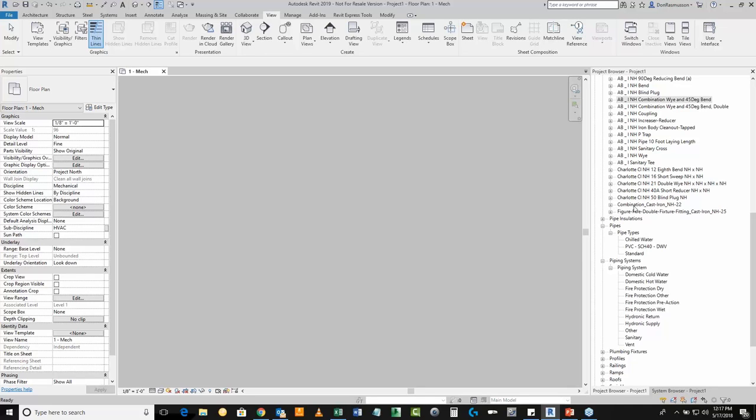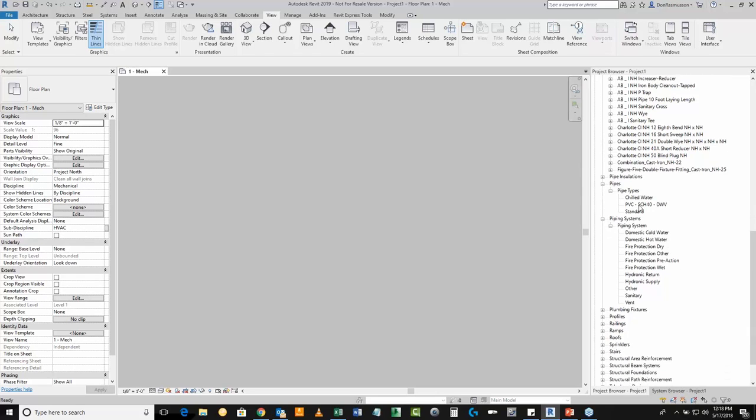The first thing that we have to do when we're thinking about setting up a pipe type and then setting up the routing preferences based upon that pipe type is to probably create a different pipe type, right? For those of you who've caught my previous webinars and or mini trainings, I go into depth about what pipe types are versus what pipe systems are. But pipe types are basically your materials and or your routing preferences.